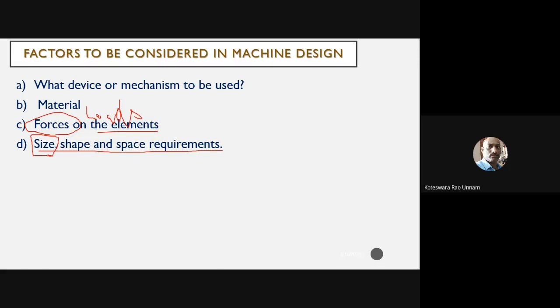So therefore, he has to take care of the size while evaluating the size of the component. He has to look into whether this size is practically feasible or not. He has to consider those points also, instead of simply taking the mathematical equations and solving them. Okay, I have taken the torque equation, I solved it, and from the torque equation I got this diameter.